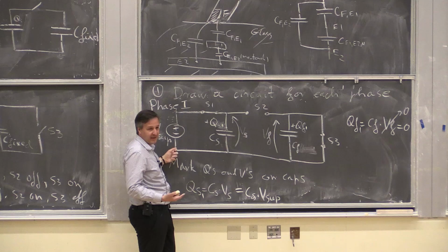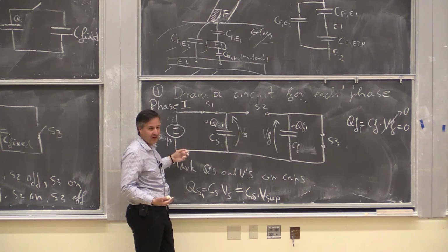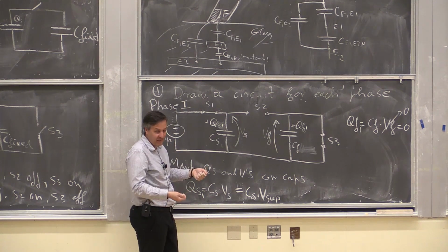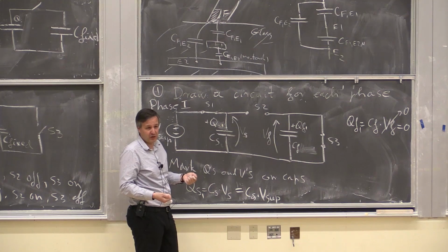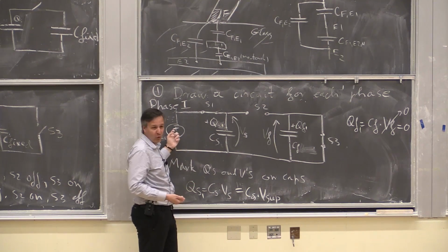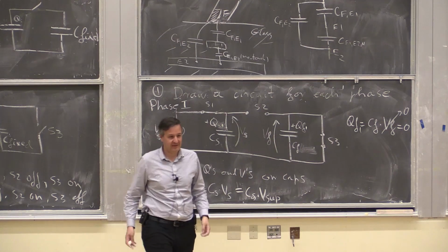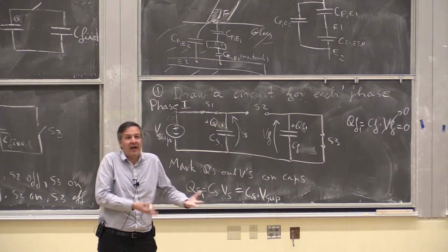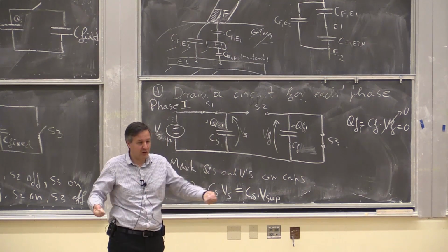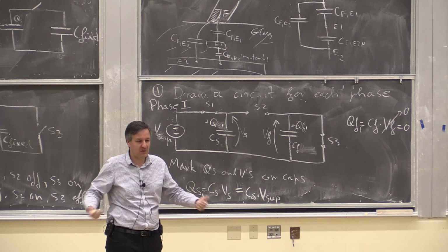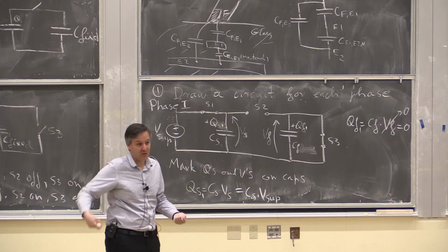But then on this side, this source is trying to keep that at VS, so that would actually be a boom situation, right? Because you're shorting an ideal voltage source, right? So that's kind of an undefined condition, essentially, because it's trying to keep VS on its terminals, but you're shorting it, so you're forcing a 0 voltage across.